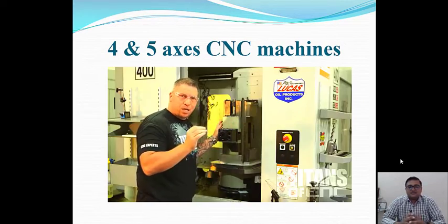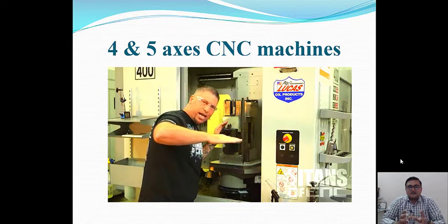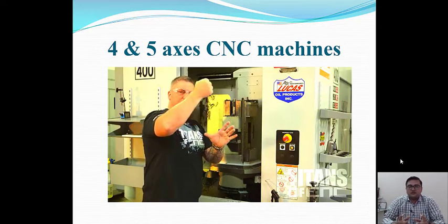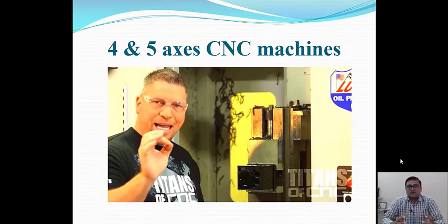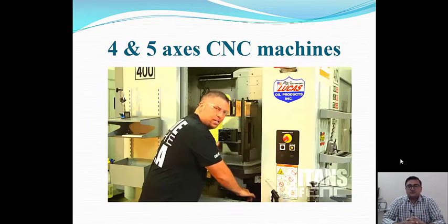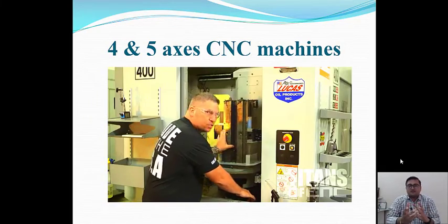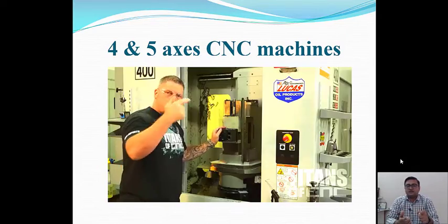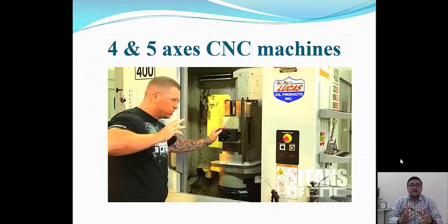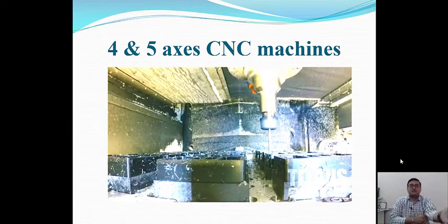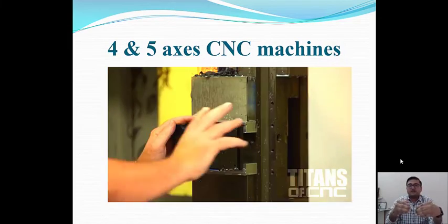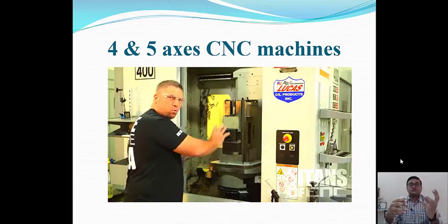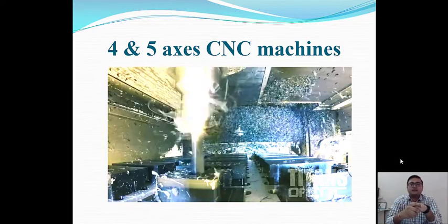See here, this particular thing is a workpiece holder, or I can say saddle, or the chuck on which the workpiece is going to be held. So this workpiece can rotate. Now see that the workpiece can be rotated here. See, the tool is working and also the workpiece can be rotated. So that is another axis, or 4th axis you can say. So 3 axes based on the tool movement X, Y and Z, and the 4th axis based on the workpiece movement at the same time.